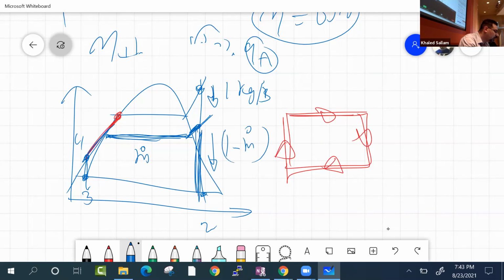So you have less work, and you think that's bad, but that steam will take that water from 4 to say 5. That heating helps the boiler look more like this: constant temperature heat addition. So that arrangement of making some of the heating happen by steam from the turbine, although it reduced the work of the turbine, really helped the efficiency amazingly. The second law likes you for doing this. Okay.